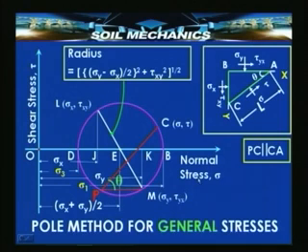Obviously, then C, which is the point of intersection of this red line with the Mohr circle, will have the state of stress given by the plane parallel to PC, that is plane CA. Then it can also be easily shown that plotting an angle 2 theta from here and joining E with C will also give you the same point C as the red line drawn from the point P. So, this is an alternative method, the so called pole method, for determining the point C.